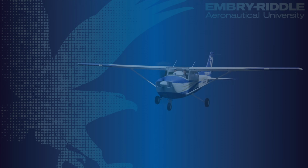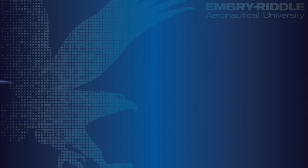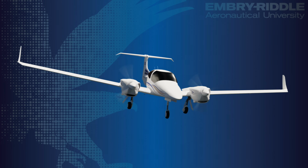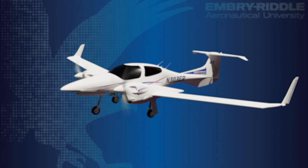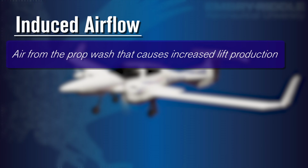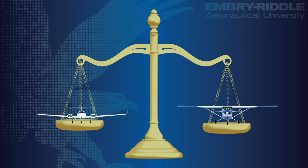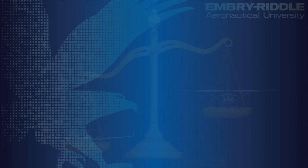Lift. The power plant is mounted to the front of a single-engine aircraft. On most light twin engines, the power plant is mounted on the wings. This results in induced airflow over the wings. Induced airflow is air from the prop wash and causes increased lift production. The added lift is beneficial since most light twin engines tend to be heavier than single-engine aircraft.